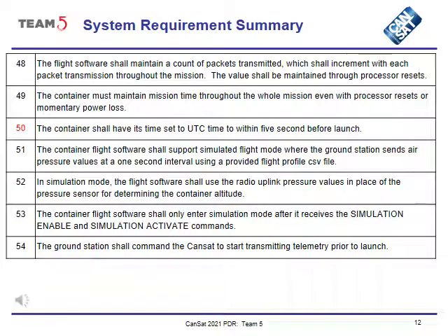48. The flight software shall maintain a count of packets transmitted, which shall increment with each packet transmission throughout the mission. The value shall be maintained throughout processor resets. 49. The container must maintain mission time throughout the whole mission, even with processor resets or momentary power loss. 50. The container shall have its time set to UTC time to within 5 seconds before launch.